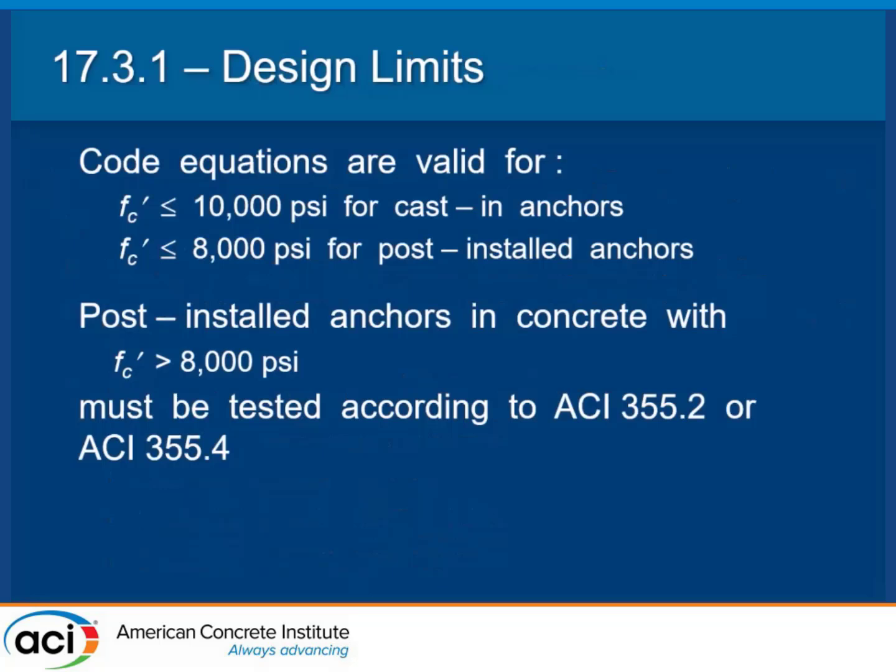We do have general limitations for cast-in anchors. We just don't have enough test data above 10,000 PSI. That does not limit you from using the anchors in concrete greater than 10,000 PSI, but in your equations, you can't use a number greater than 10,000.